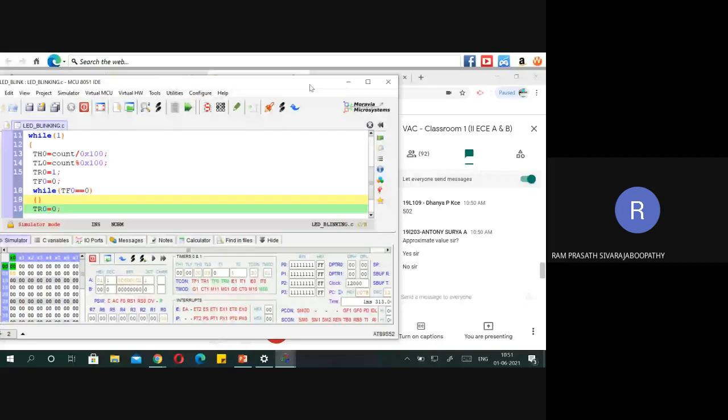See, when you are programming a timer for your real-time application for accurate timing, definitely you have to go for interrupts. Then only it will generate exact timing. Here there is a 2 microsecond delay, correct? It is because it keeps on checking the condition. After the 500 microsecond timing is over, it comes out, and testing that condition takes some 2 microseconds. Am I right?